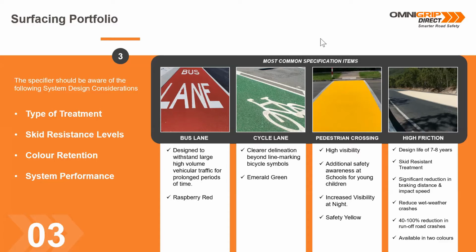And the fourth one is the high friction surface treatment. So this has got a design life of between 7 to 8 years. As Louis had mentioned earlier, very, very important in curved bends, high accident zones, black spot locations. And what this does is provide a significant reduction in braking distance and impact speed. It also contributes to reducing the wet weather crashes.